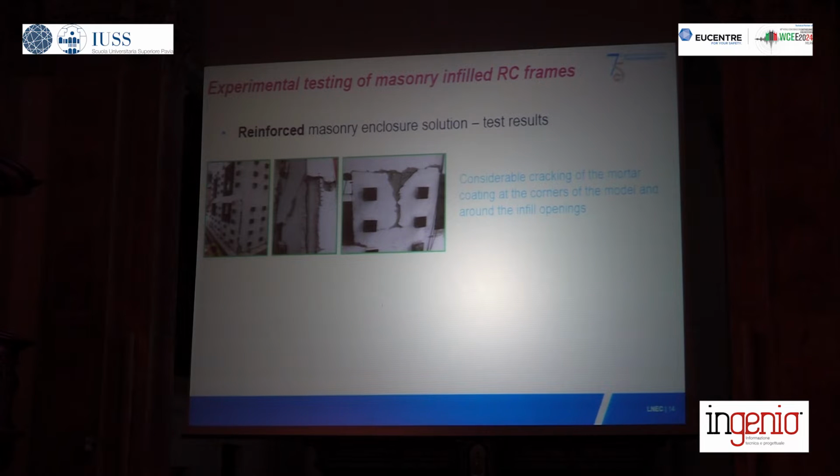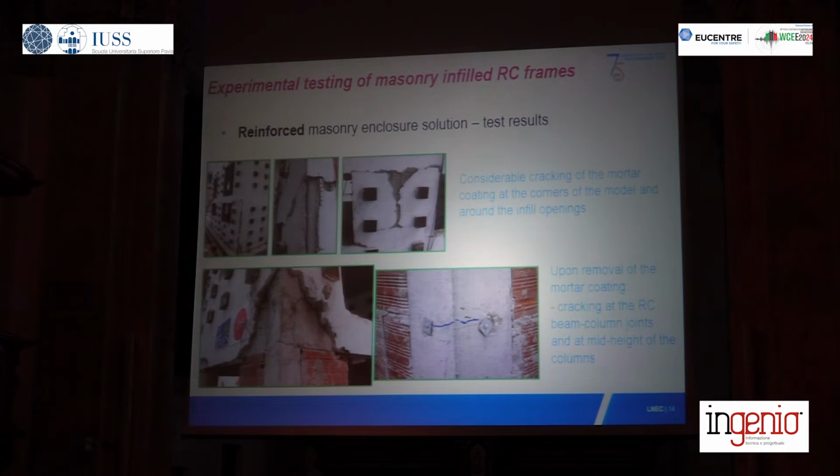But when you go and look into the details of the response of this retrofitted or strengthened building, you see that you still have considerable cracking of the mortar coating, and when you remove this mortar coating, you see that, for instance, at the joints you have significant cracking.